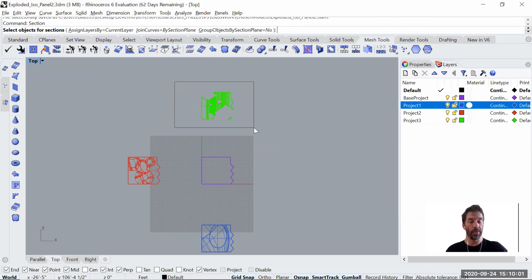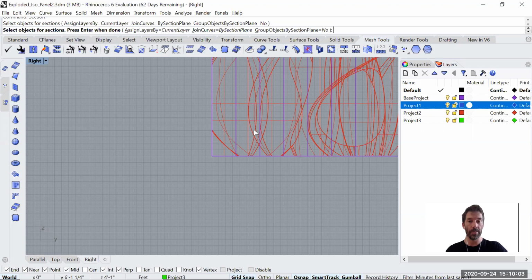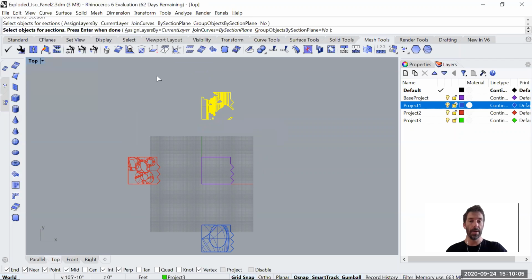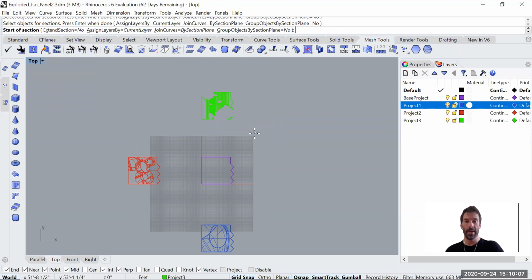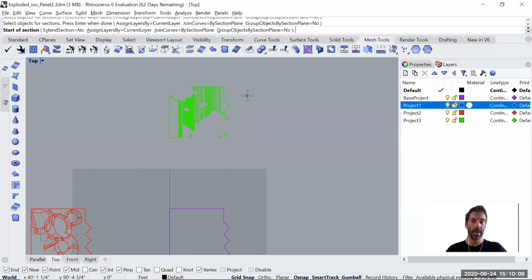And what I did is Control Tab, so that's why I go fast from one to another, no? I went to the top, selected the entire thing, press enter, and I'm gonna do sections, means vertical cuts. That's why I go to the top view. And I'm gonna say from here to there, but I'm pressing Shift to make sure it's orthogonal, or I click on orthogonal to make sure it's orthogonal. I like to press Shift, which is a shortcut for orthogonal.